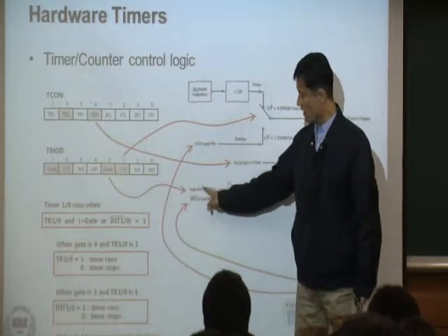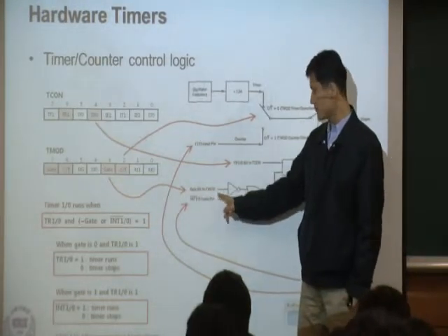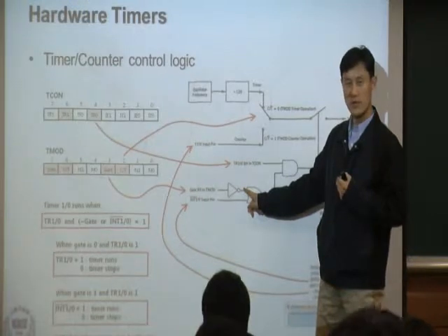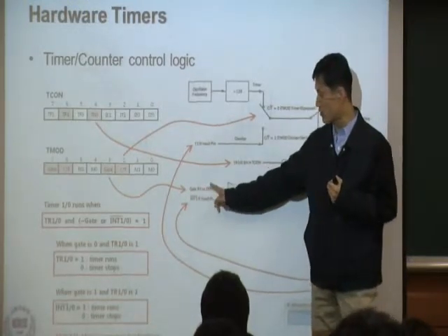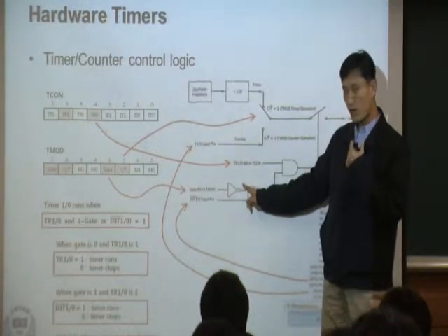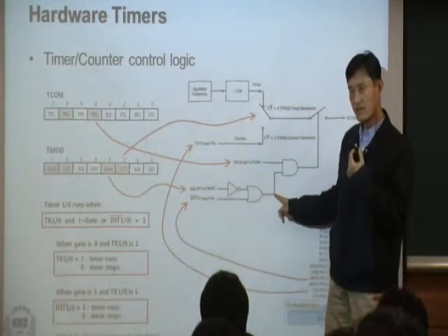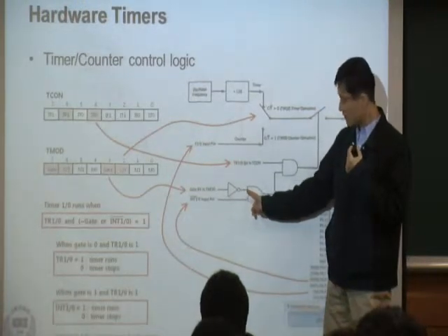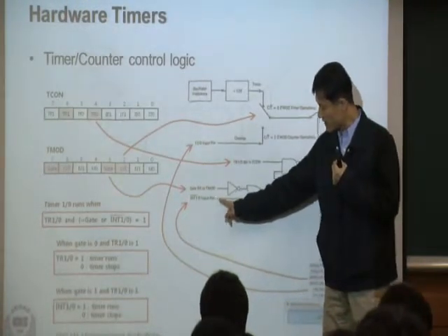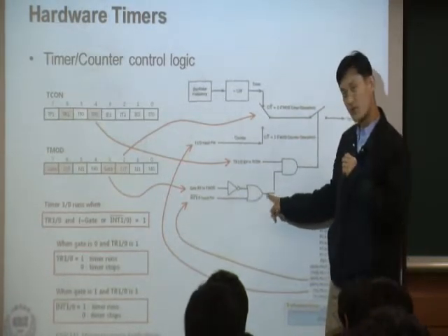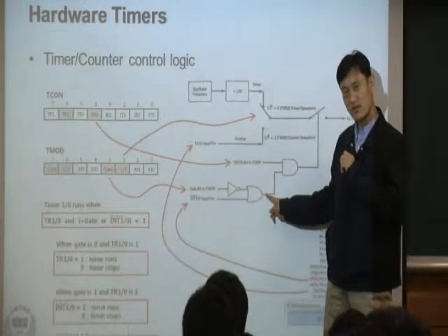If you make this gate bit to be 1, now what happens is this right here is a 0. Okay? Because I have a gate bit to 1. This is not gate. So here is a 0. What we want eventually is 1 here at the output. But we have a 0 here. So therefore, now if this one is 1, we have a 1. If this one is a 0, then we have a 0. So it's like a gating now.